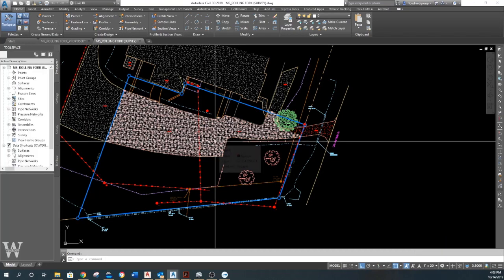I need the total acreage, or total project size. I need it in acres, and I need it in square feet, because my data will be input that way. Then I need my existing impervious area and my existing pervious area.